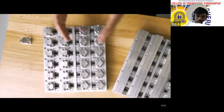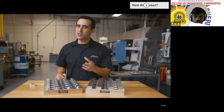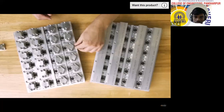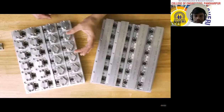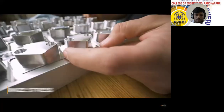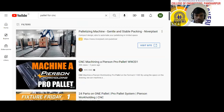You'll also notice this pallet is a mirror image of itself. The reason for that is that if we continued the pattern, the back sides of the clamp would have a thinner section of material to press against. In this configuration, the broad side of the workpiece is contacting the outer edge of the pallet, which spreads the force across a larger area and lowers stress on the